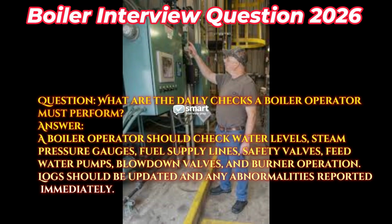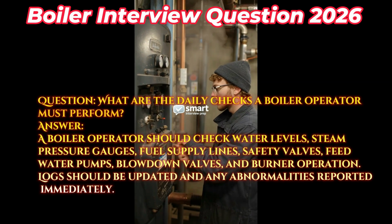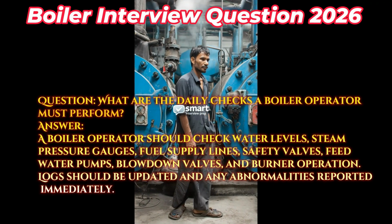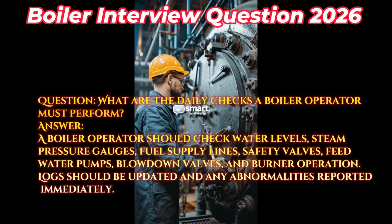Question: What are the daily checks a boiler operator must perform? Answer: A boiler operator should check water levels, steam pressure gauges, fuel supply lines, safety valves, feed water pumps, blowdown valves, and burner operation. Logs should be updated and any abnormalities reported immediately.